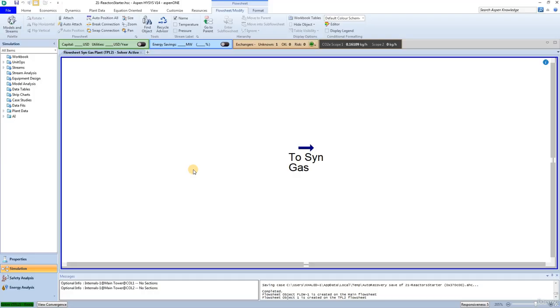If methane is present and combusted, it can be reasoned that any other hydrocarbons would be combusted as well. To simplify the reaction definitions, you will remove any hydrocarbons heavier than propane prior to feeding the gas into the first reactor, thus ignoring the combustion of any heavier hydrocarbons.